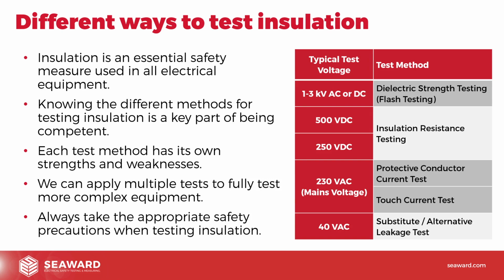So although they're not insulation resistance tests or insulation strength tests, they're doing the same thing. The only difference is we're measuring in current rather than resistance. But as we looked at in previous sessions with Ohm's law, that's just an equation. So we can work out the insulation, we can work out the current. It's basically just two halves of the same thing. So the protective conductor current tests and the touch current test give us options to test equipment.